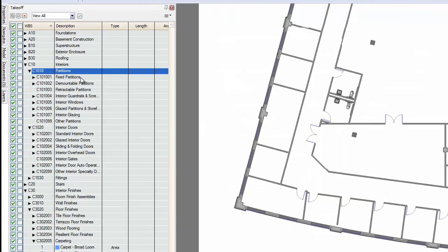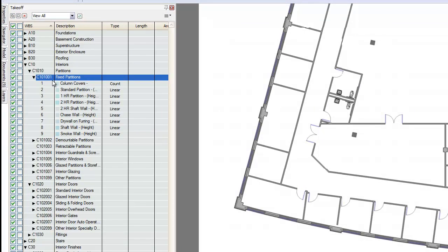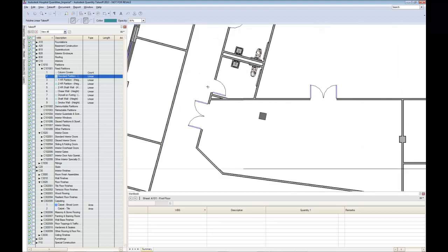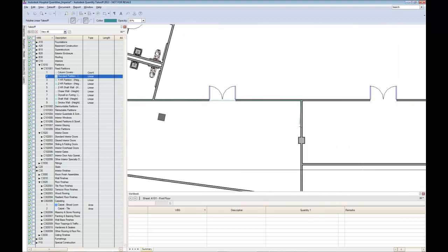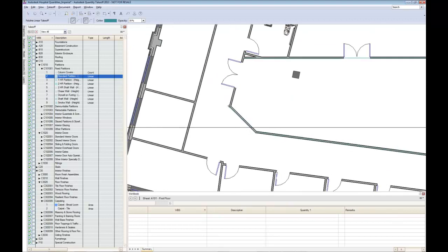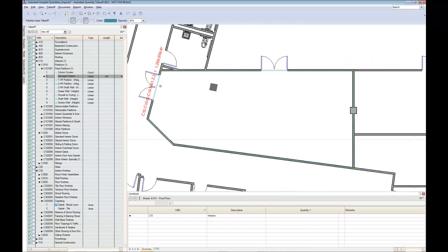Here we see a floor plan for the preliminary design brought into Autodesk Quantity Takeoff. We will leverage a catalog of standard building components to begin to quantify and classify the data provided using two-dimensional takeoff tools. Note we can do linear takeoffs for things like walls and partitions, and that once digitized, we get a worksheet of the quantities generated that keeps a running tally of the information.